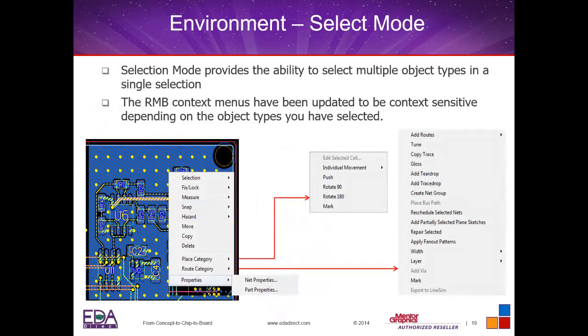There's also, in that select mode, a right mouse button. Once you've selected something, since it's going to push you right into that mode, whether it's placement mode, route mode, or drawing mode, by pushing the right mouse button you're going to be able to activate the commands that you can use with that tool. So very easy to do. Select something, right mouse button, push into whatever you're going to be doing, whether you're routing, adding components, or moving reference designators. So very nice, easy environment in the select mode.